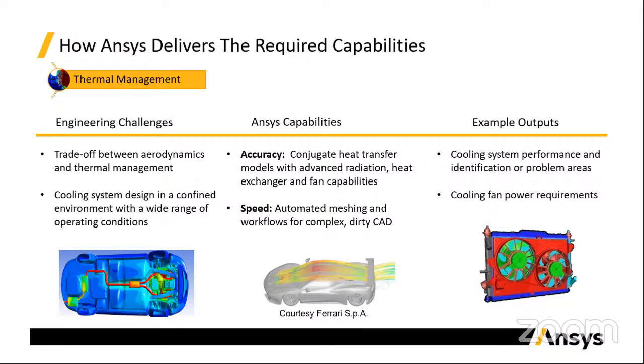And even on the pre-processing stage, Ansys has a lot of tools, especially nowadays with the more recent releases, wherein you can work with complex dirty geometry and easily use wrapper-based meshing technology to prepare your domain for the CFD simulation, right? And then in cases like these, you have cooling packages themselves. It is not efficient to actually model the geometry of those cooling packages. So there are some simplifications that you can implement within the Ansys Fluent framework.